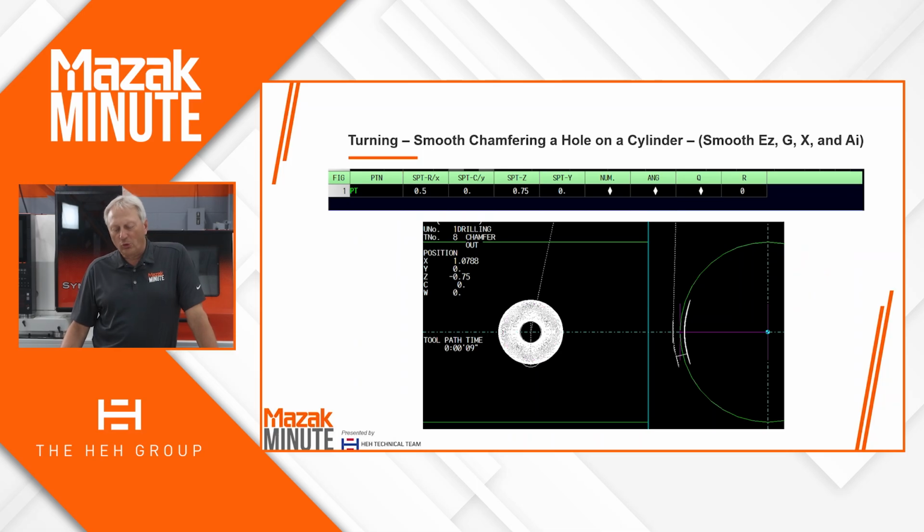So when we go to look at the toolpath, the biggest thing that you're going to notice is that on the position page, it's going to move over in X, Y, and Z, and the C-axis to the beginning or the center of the hole. And then it will come down in the X-axis, and it's going to arc into the cut. And if you look on the right side, you can see how the toolpath goes about.